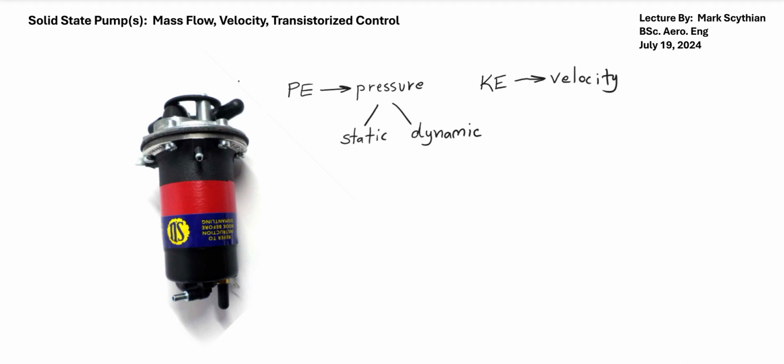We have the input side, so we'll assume this is the P1 on the input, and let's say we have a primary. We could move that over, the input side is the P1, and we'll say this is the output side, the P2. And again, we're dealing with the absolute pressure. Where relevant, if it was a liquid system, then we have an ideal fluid, and so only the hydraulic pressure would comprise the overall absolute pressure. But if we're dealing with a gas, then we have to include the atmospheric pressure as well, call that ATM.